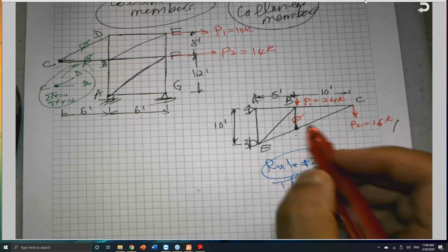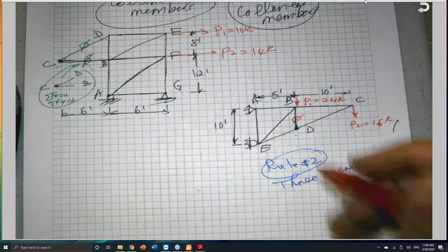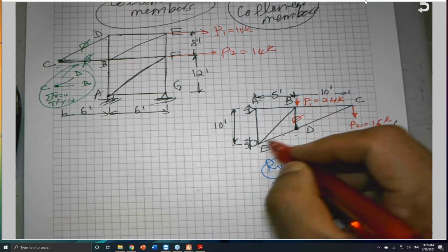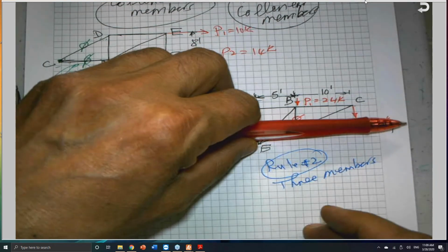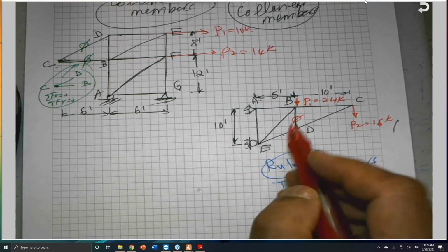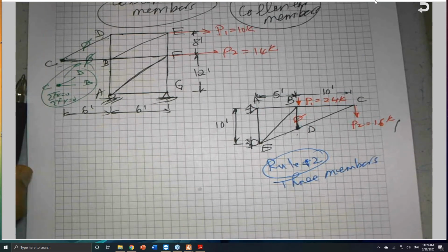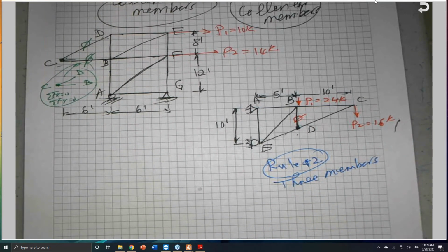Because if you take this joint out and analyze it in the x direction, this member FDC and FDE, they have components along the x direction, and they must be equal for equilibrium. Again, this is equilibrium. So this is a zero force member. Any dispute about that? Or any disagreement about that?